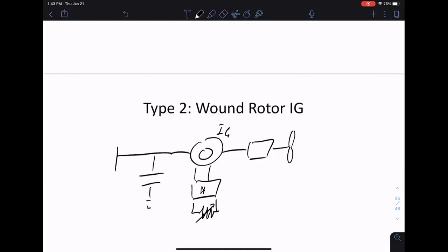Okay, so what you'll see in machine design, turbine design, is often the trick is to get rid of power. It's not generating power, it's how do you get rid of this excess power? How do you dump this power in a short amount of time? So this one idea to dump power is to just add a resistor in parallel with a switch. You dump power when you close the switch. So this is a really simple idea. This is obviously inefficient if your control mechanism is just burning power as heat.